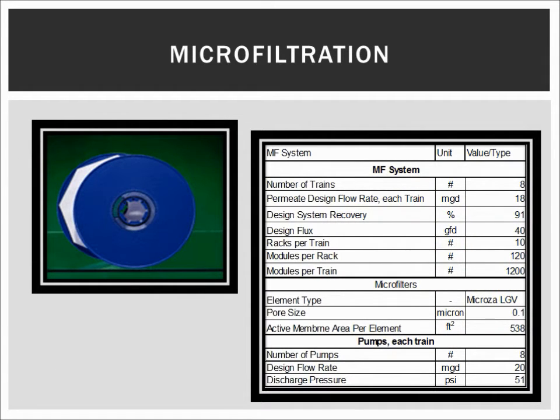Microfiltration is the next process involved with the seawater treatment. This process prepares the water for RO treatment by filtering out small particles and bacteria, which increases RO efficiency and prevents fouling. Microfiltration is accomplished by pressurizing water into a tube, where the particles and contaminants are then strained through tiny hollow fibers as small as 0.1 micrometers.